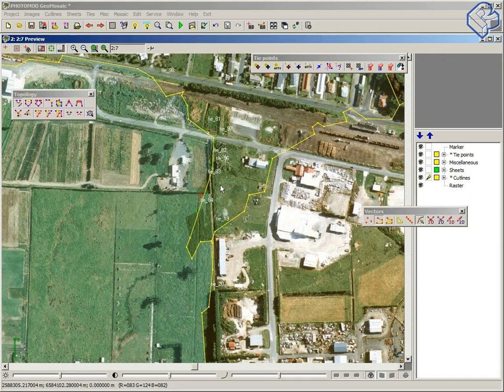It's easier to create new vertices than edit existing ones. And with Control, I just change the place of this point and delete this one. Just click to select the needed vertex and press the Delete key on the keyboard.